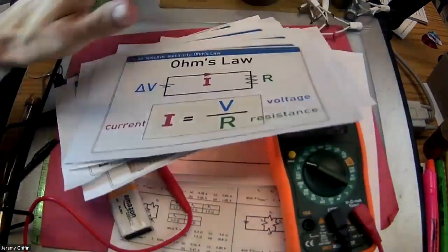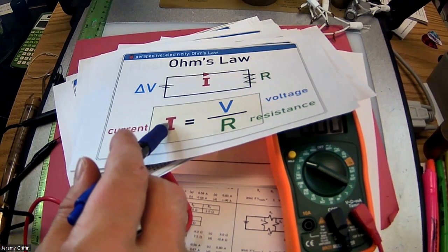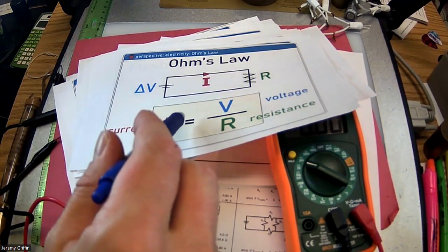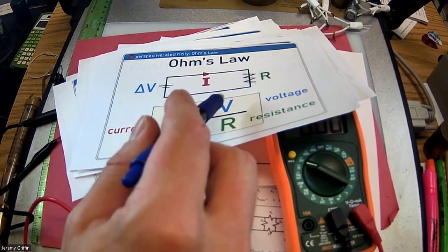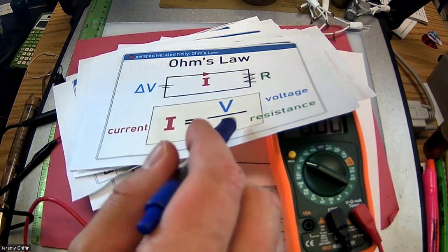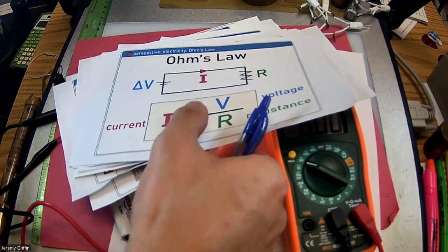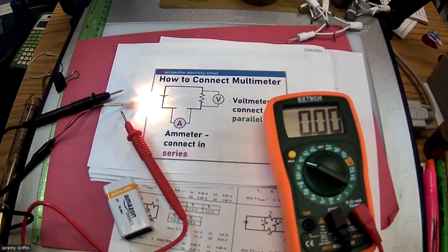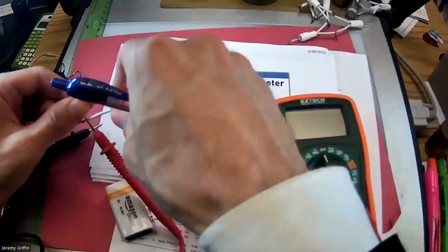Let's go way back to Ohm's law and put this all together. So Ohm's law. You guys saw 2 amps. You guys saw 5 volts. Cross multiply resistance, divide this down. So 5 over 2, that's like what, 2.5. So that resistor is about 2.5 ohms. I said that bulb was about 2 ohms, so that probably fits in that window, right? They're all slightly different, but right about 2 ohms.